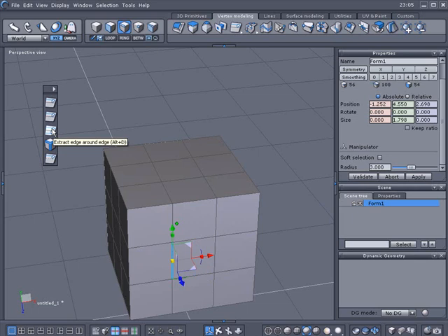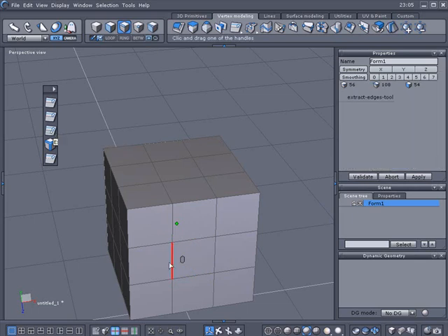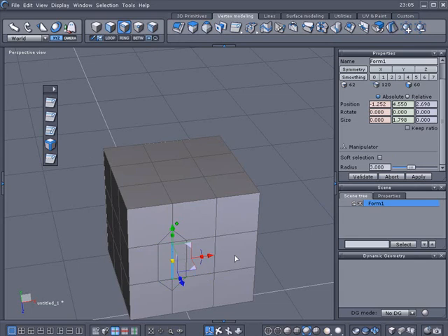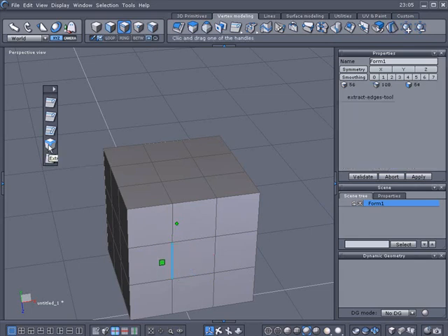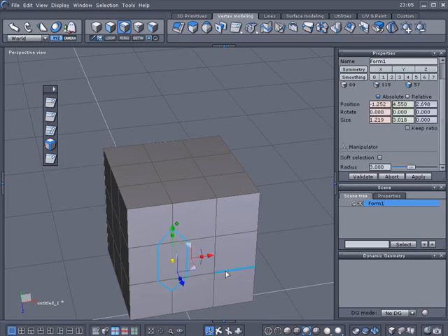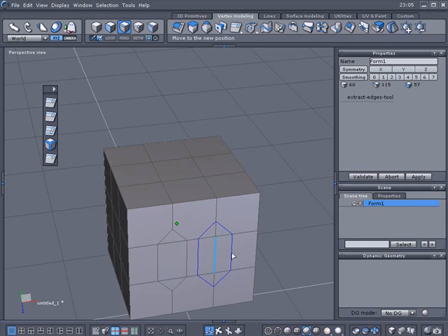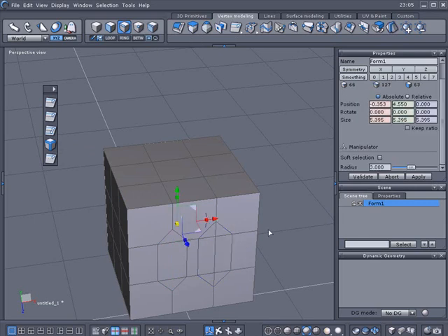And we'll do the edge around edge. Select here. As you can see, it's going around it on each side and let go. Now look how that looks there, and I'll Control Z that. And the fillet will almost do the same, but it will remove the center edge here. So basically they're the same almost. So I'll just do another one over here. I'll just do a little comparison so you can see them. You can click here and shift click, and you can do multiple ones at one time.